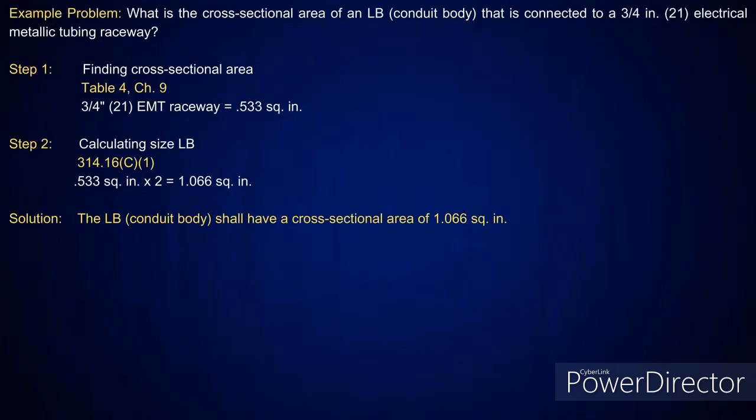Yeah, it takes time to do all that, but I think it's worth it in the end. Now, this is possible, could be on your test. They may want to know if you know how to find the cross-sectional area of a conduit body. And we're going to show where you're connecting to a 3/4 inch electrical metallic tubing.